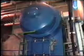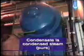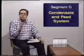After all, the condensate, which is condensed steam, is as pure as you can get. And so, consequently, is the boiler feed water. Because of this, the makeup must also be high-quality water. And this is usually produced in a demineralizer. Now, this is opening up another subject. The chemical control of feed water and boiler water itself is a very important part of boiler operation. And we'll be talking about this in the next segment.